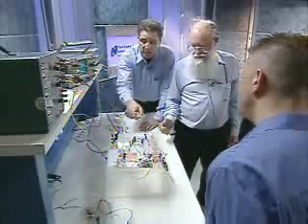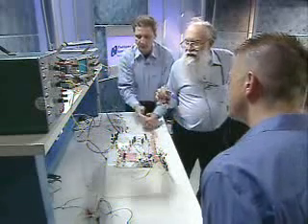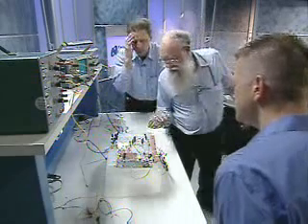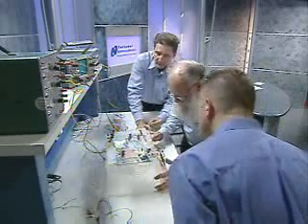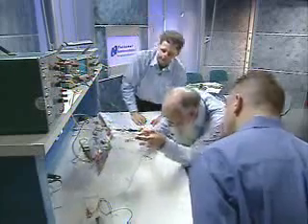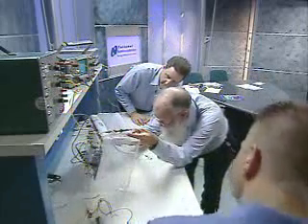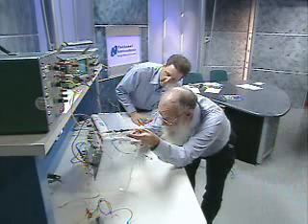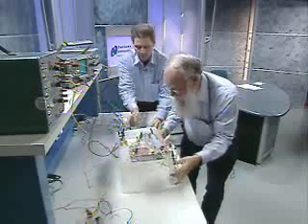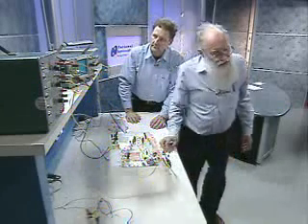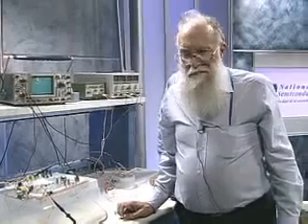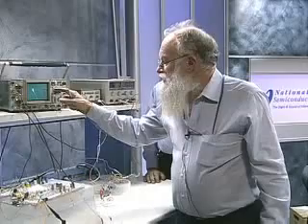So now, where are the 200 ohm resistors that were the balance? Is it a pod or two discrete resistors? No, they're inside there. Wait a minute, I can lift this up. No hazardous voltages in this one, folks. So the 200 ohm resistors are here and here, and here and here. So we do fool around with precision 200 ohm resistors to help us evaluate a 1 milliohm resistor. That's great stuff. So this is the error voltage we're looking at.